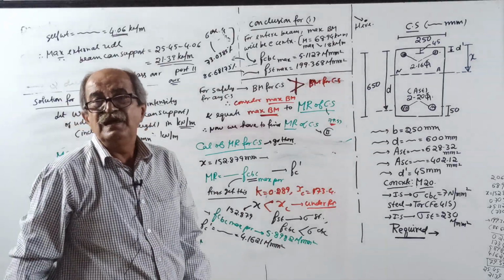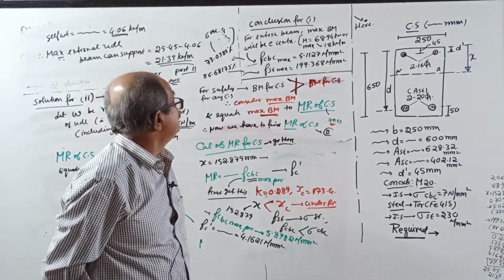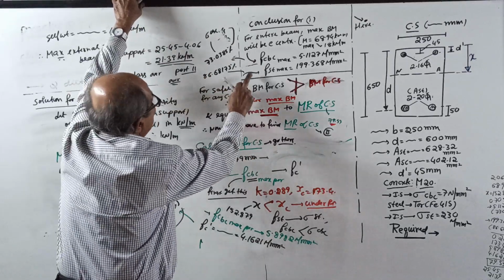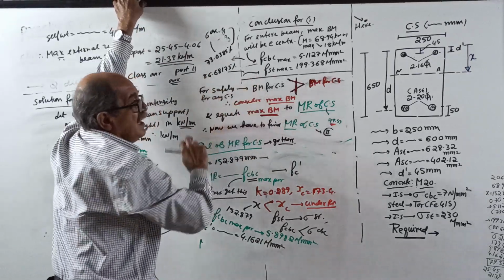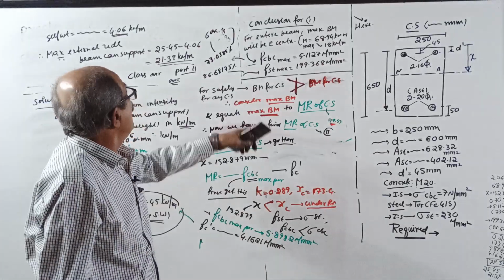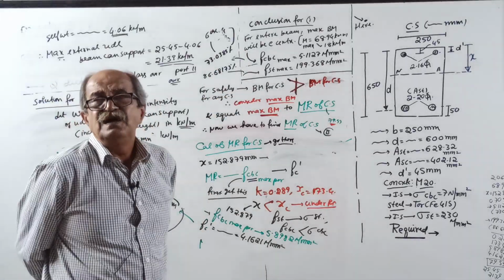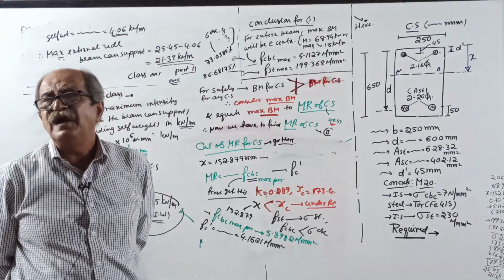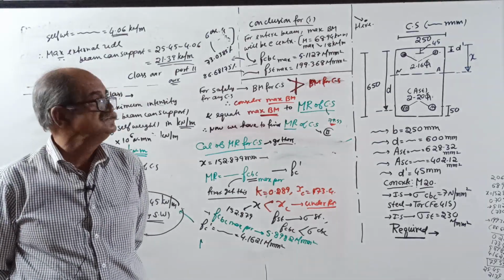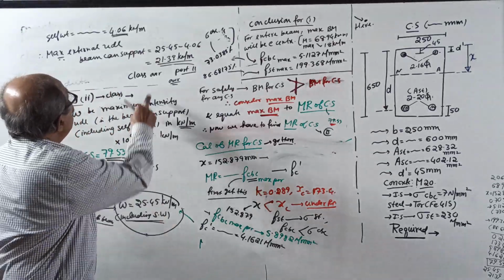That means linear variation, working stress method. See, the stress in steel has already reached 86% of the limit, but concrete reached only 73%. This clearly tells it is an under-reinforced section. Oh, is it that way? Yes. Okay. But still tell me, how you got this number?